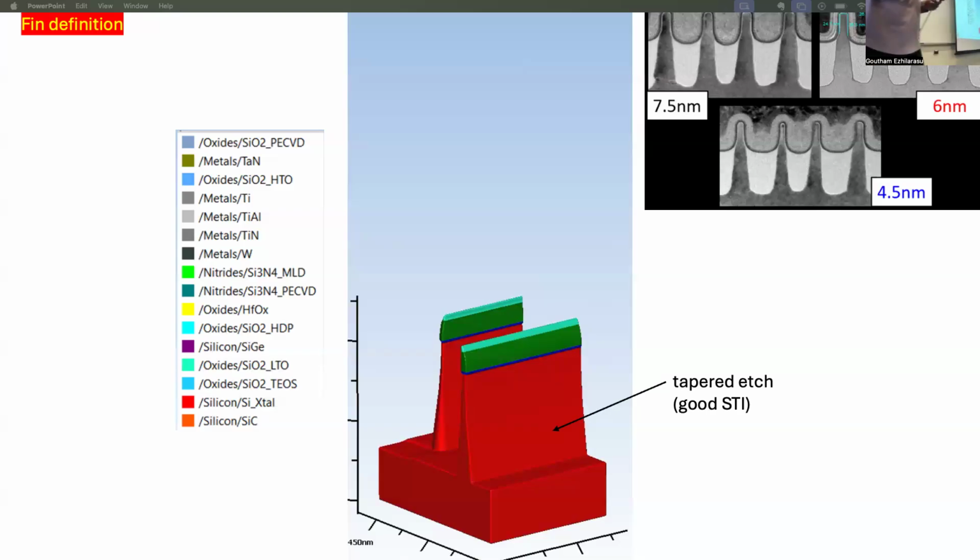I'm going to do that with doped polysilicon. I'm going to dope the fin, okay? How you do that is, say you have silicon, and you want to dope the silicon N-type. What you can do is deposit on top of the silicon. Usually there will be some layer here, which is called a diffusion barrier, usually made with a thin layer of oxide, okay?